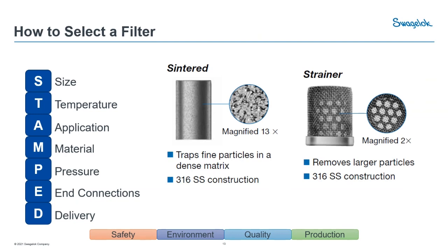So a common issue that we see could be abnormal pressure drop or reduced flow downstream of that filter. This is typically caused by a clogged element or a clogged filter housing. What we want to do in that case, change the element, see if that solves it. If that clogging continues to be a problem, if it happens too fast or too often, you may need to consider changing your maintenance plan to do that more often.